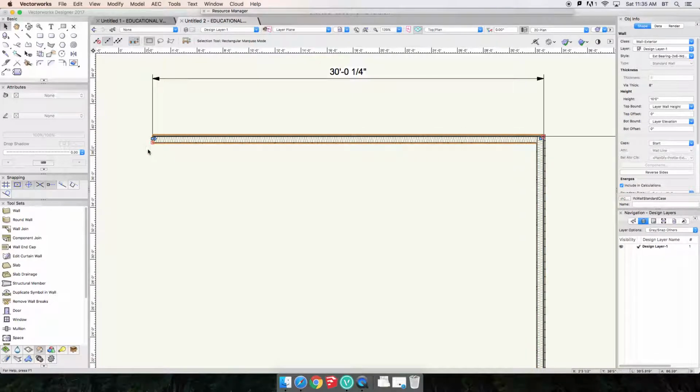The square and triangle differentiate the ends, because when we have a line, it doesn't matter which end is which. This square and triangle represents the start of our wall. So if I'm starting from this point, this is the left side of my wall, this is the right, this is the end. We need to know so we can know which side is left or right.